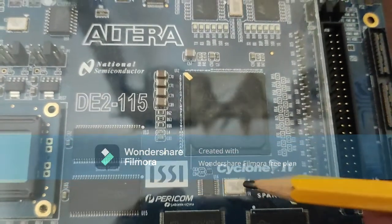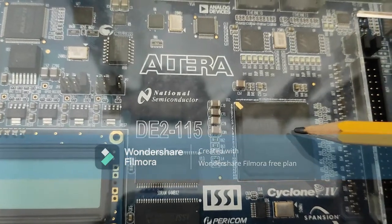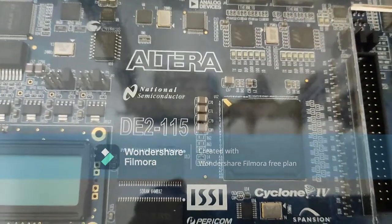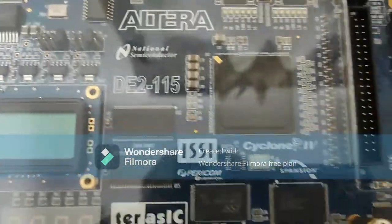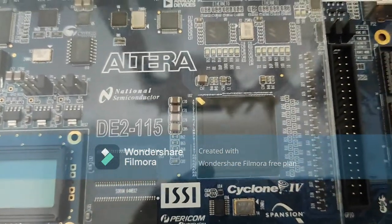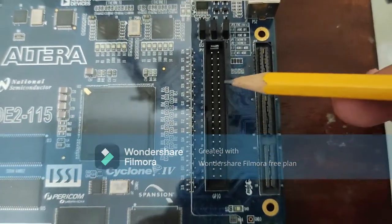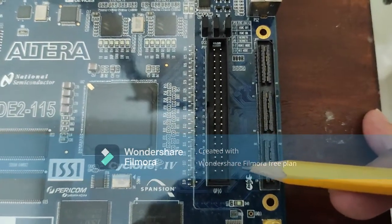50 megahertz oscillator. And this one here, the big one, is the Altera 60 nanometer Cyclone 4E FPGA with 115K LEs, okay? And this one here is the expansion, this one is the expansion header or J15 with protection diodes.